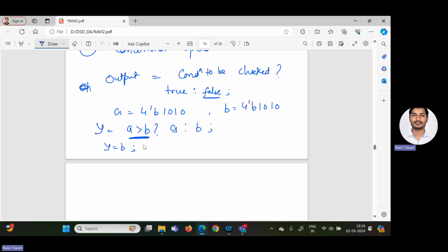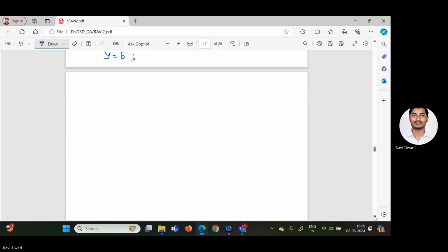Now we will see some extra questions related to direct values. For example, they are giving some expressions like this. A is equals to 1'b1, for example, you take. B is given as B is equals to 2'b00. C I am taking as 2'b10, and D I am taking as 3'b110, for example. I am writing Y is equals to {B, C}.